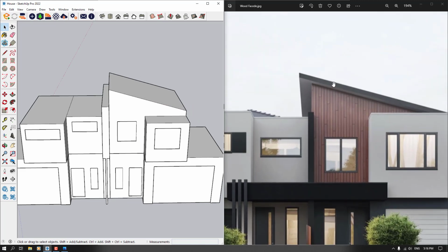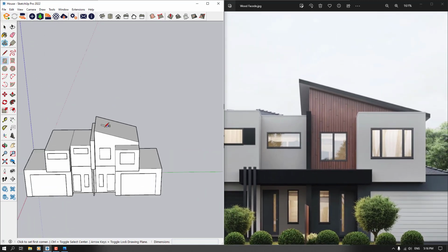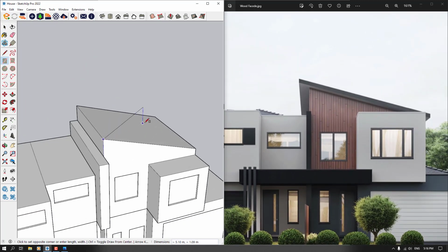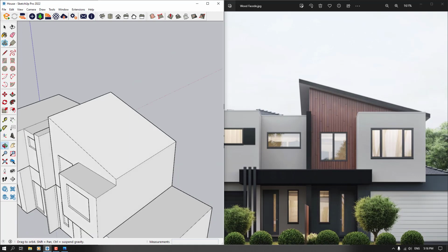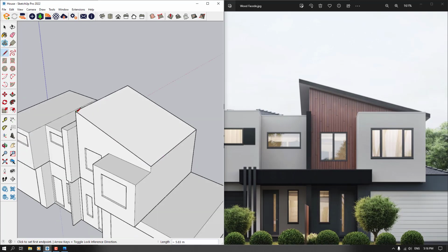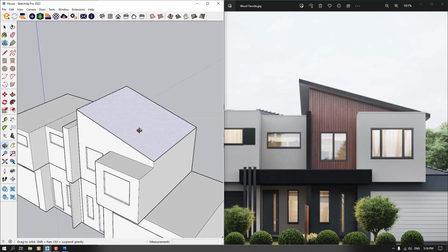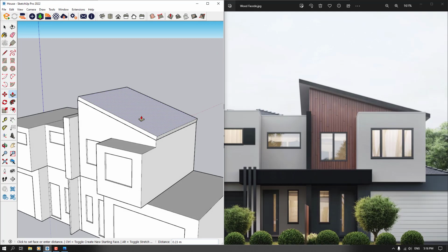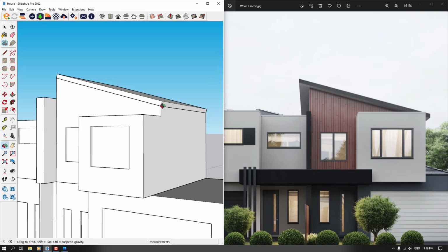We have the roof in here, so I'm gonna select my rectangle tool and draw some rectangle on this side, but we can't, so I'm gonna use the line option from here to here and here. So we have some extrusion in here, something about 10 centimeter maybe, or 20 centimeter is good.